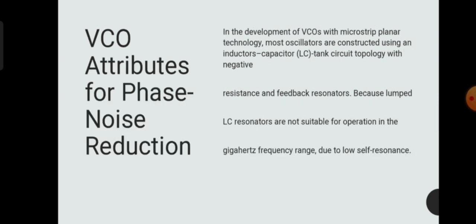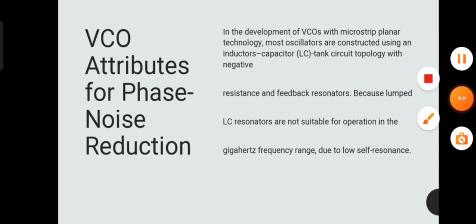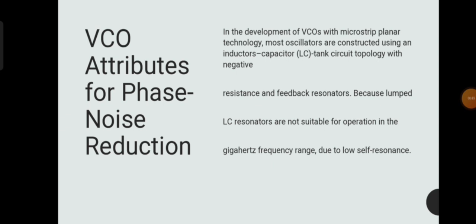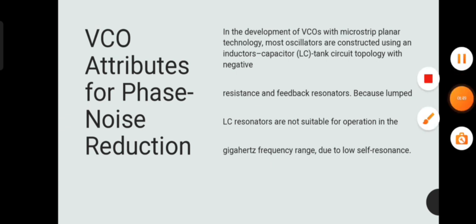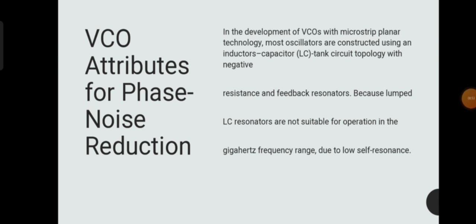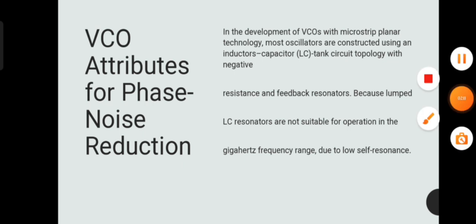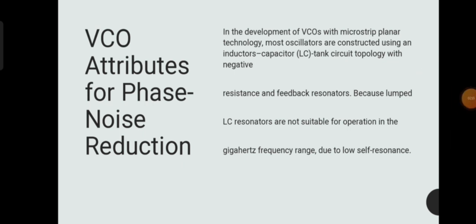VCO attributes for phase noise reduction. In the development of VCOs with microstrip planar technology, most oscillators are constructed using an inductor-capacitor tank circuit topology with negative resistance and feedback resonance, because LC resonators are suitable for operation in the frequency range due to low self resonance.